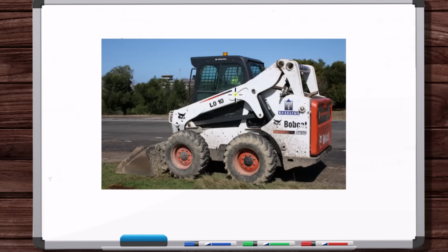Take a snapshot of that, and at that moment, bring this component into empty space. And then maybe you'll analyze some worst-case scenarios. So fill the bucket, overfill it with gravel or cement, raise it really high in the air, take a snapshot there, and then bring this component into empty space and apply the forces then. That'll be two different free body diagrams for those two different scenarios.